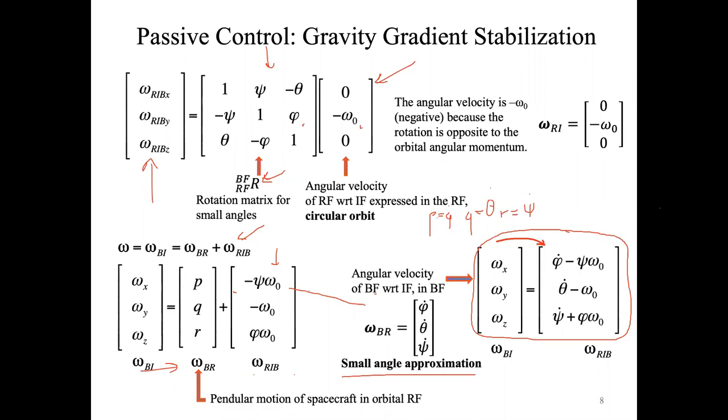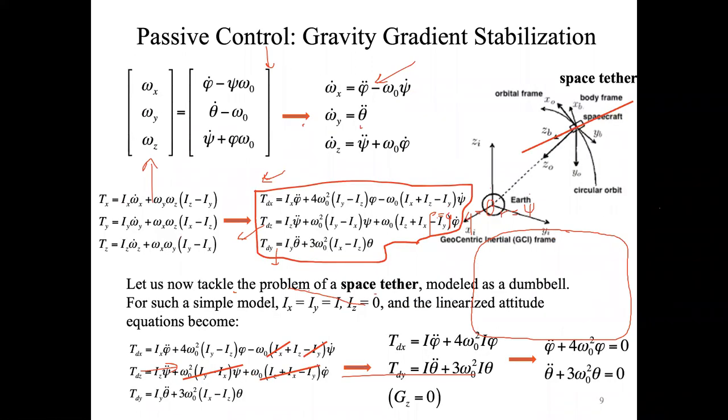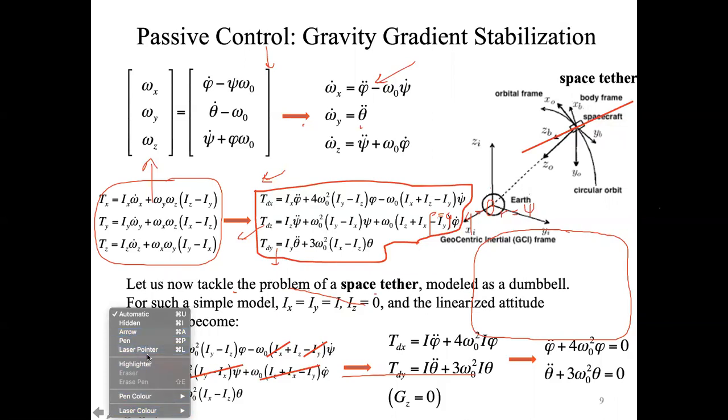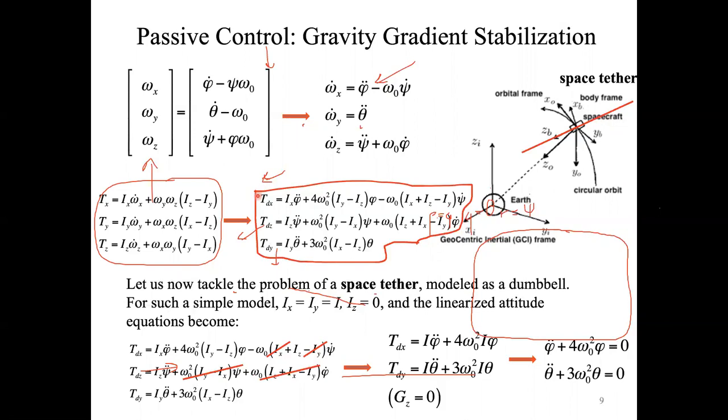So we are able to express these nonlinear second order differential equations in a set of three equations that are linear and are written with respect to the roll, the pitch, and the yaw angles.